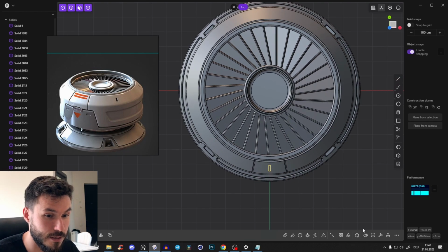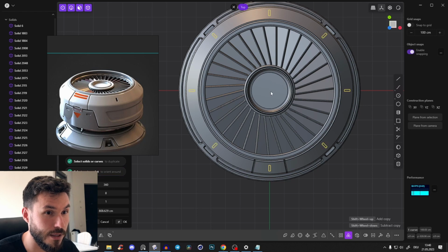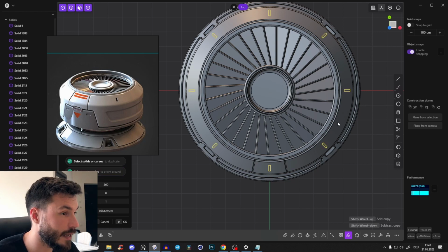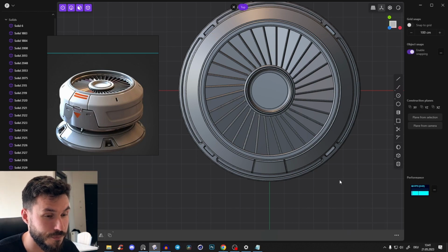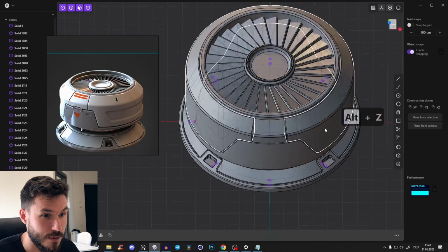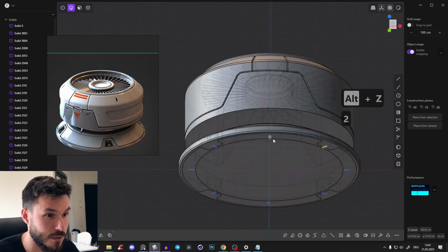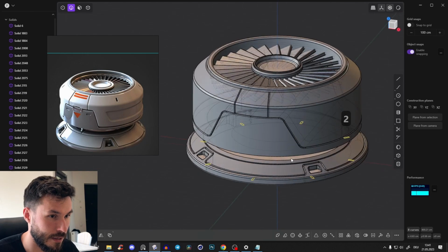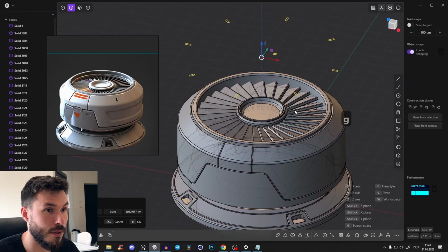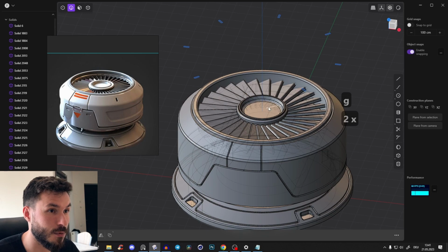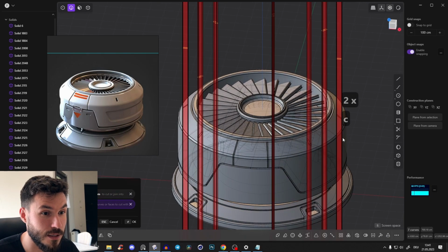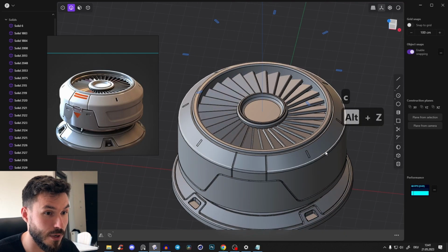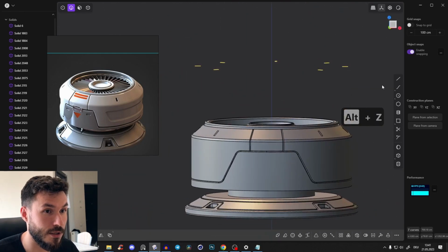So while this thing is selected, again, radial array to the middle. And that looks exactly what we need. So right click. And you lost them, because they are here on the ground. So just select them one by one, and just bring them up for now with G. And we don't need this one here. So again, select them all, press C and select this body you want them to cut. Again, just delete all of them.